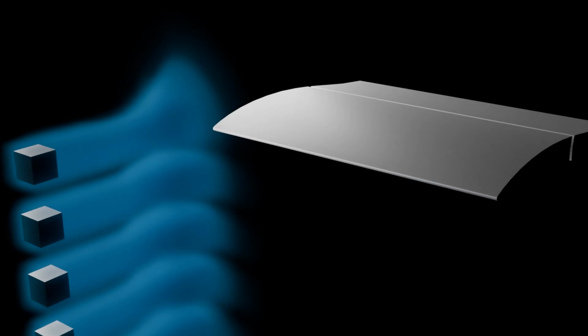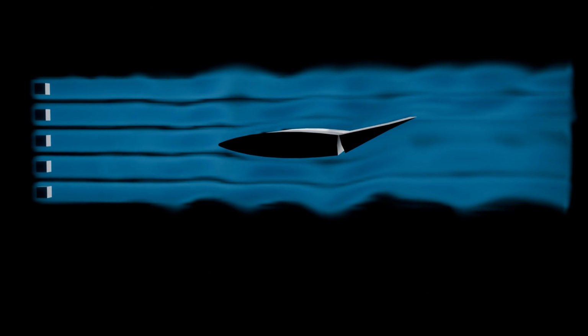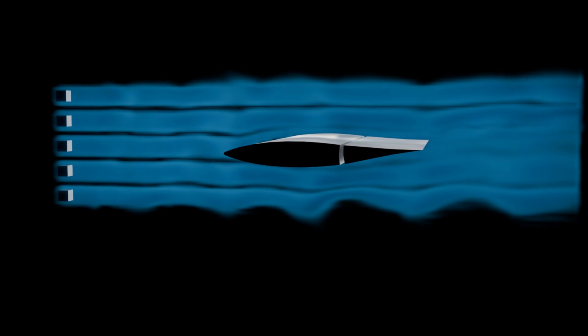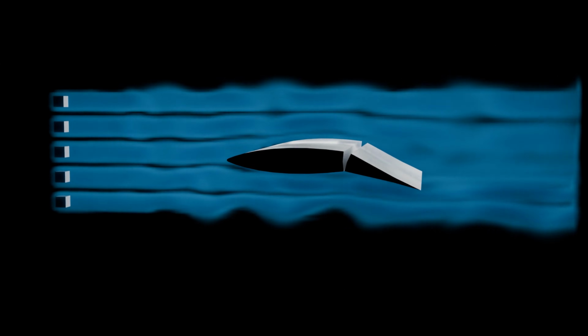Each control surface, rudder, aileron, or elevator, works much like a wing. But unlike a fixed wing, they are adjustable. Instead of generating lift, they create directional aerodynamic forces proportional to the pilot-introduced deflection. The airflow changes, creating a pressure difference that moves the aircraft in the opposite direction.